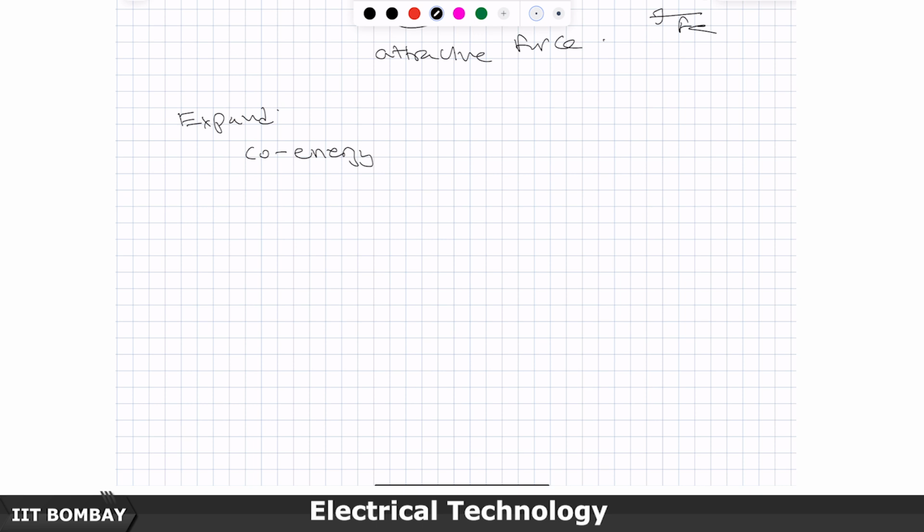But to begin with, we will have 1 degree of freedom on the mechanical side, but on the electrical side many electrical sources will be there in a 3-phase system. So, we need to expand this concept of co-energy F e for at least 2 electrical ports, and then we will go to multiple also, and 1 mechanical